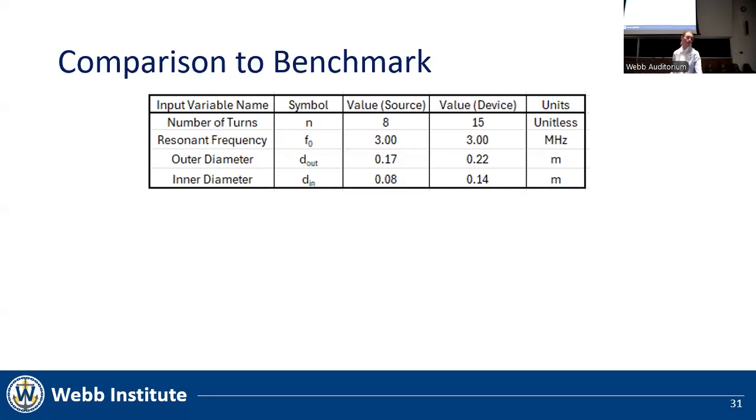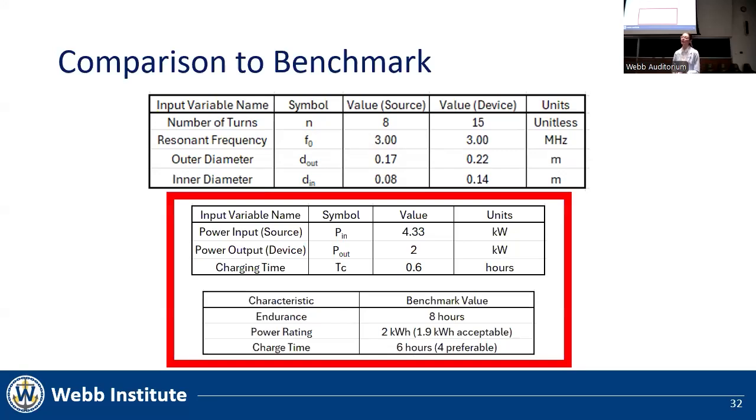concept system to have. The bottom two tables compare that essential part of the powering requirement. These are all the requirements that are met, with the top table being what the system must be in order to meet those power requirements. The power of 4.33 kilowatts would charge the 2 kilowatt hour rated lithium-ion battery in approximately 0.6 hours, assuming a 30% extra charge time given the decayed rate of charge. This is also in due part of the 0.6 maximum efficiency of this design.